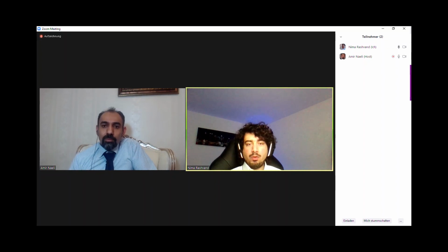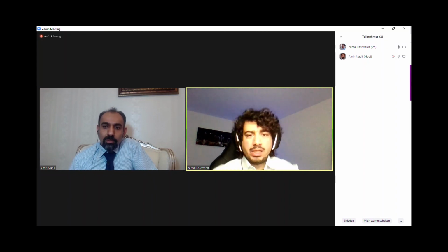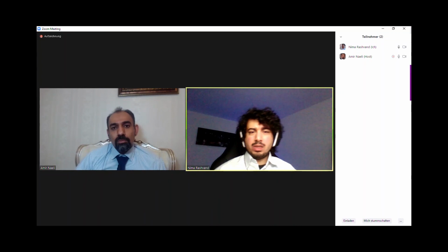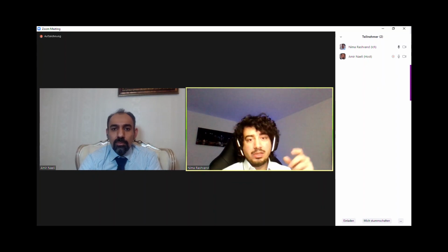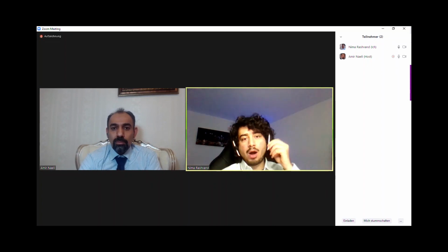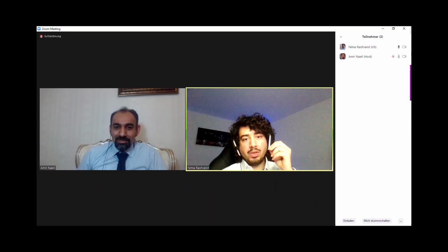When I was working with one Italian company, their fillers had a very interesting feature. Maybe I can say that this was an additive feature that could be considered as a competitive advantage. The filler nozzle actually had a kind of suction functionality. So the last drops of each filling for each bottle were taken back, so it won't leak even a single drop.